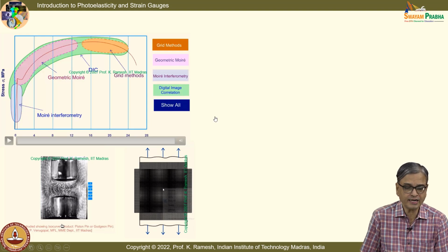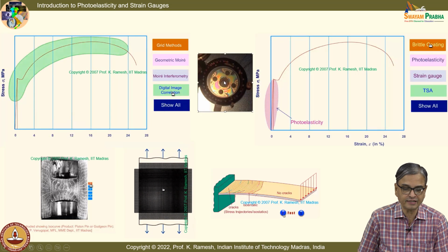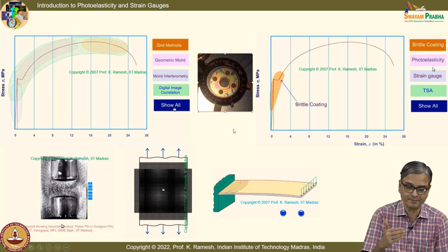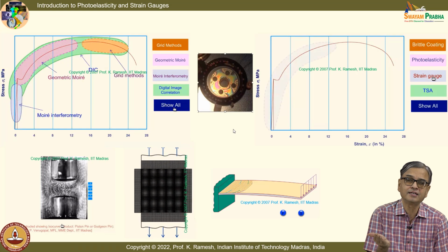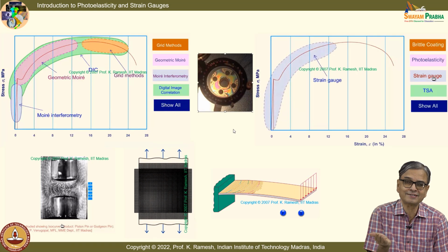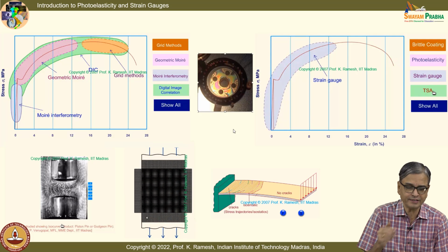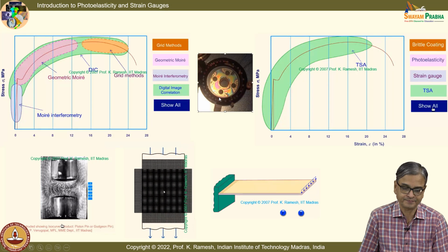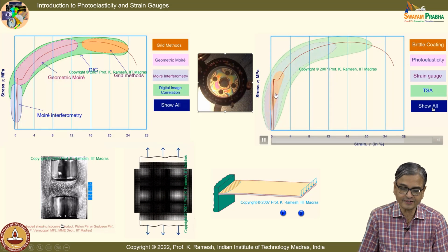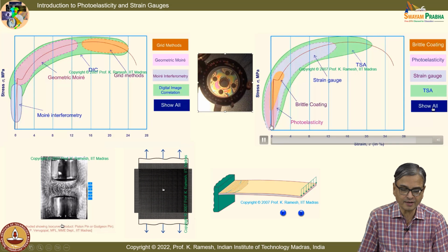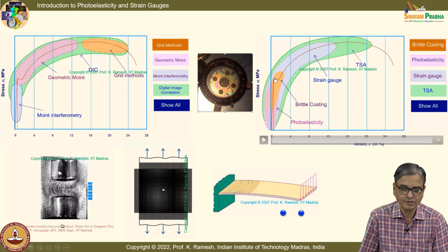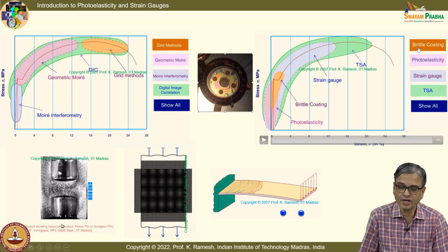And we have also looked at photoelastic coatings, and in the reflection scenario, you have the coating bonded onto a specimen. So, the strain from the prototype or the specimen is transferred to the birefringent coating. So, it is strain induced and you get beautiful fringe patterns. So, you have photoelasticity which is in this range, the complete elastic range from almost close to 0 strain till yielding. Then you have brittle coating.